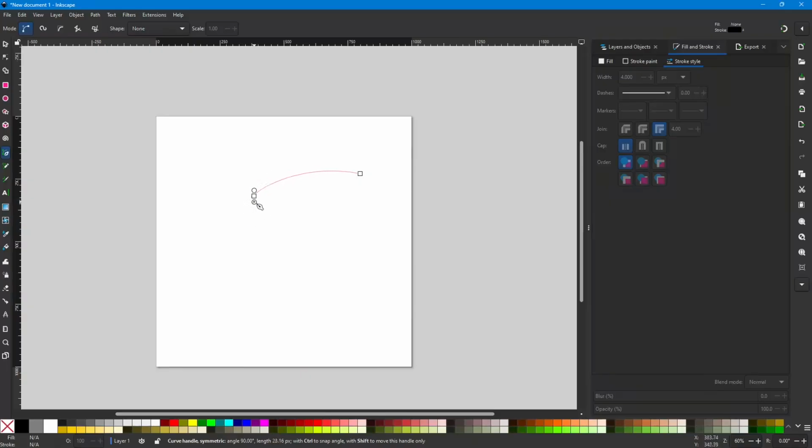You can see the control handles are working, they're mirroring one another. Wherever I put one, the other one goes opposite, and it's the same distance away from the node that they're operating on. So I'm just going to set that one by letting off, and now you'll see I have another curve because this handle set the control for this curve. But watch what happens if I click and let off. It locks in the previous line, but I have no control handle because I'm not dragging.